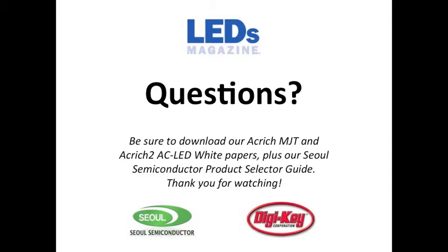So you talked about the flat top and the dome LEDs, and mostly I think you talked more about optical, and I might have a question there, but this person wants to know, is there an efficacy trade-off between the flat and dome type? That's a good question. Typically with a dome type, you're going to extract the light a little bit better. In flat type, I think I'm seeing 145 lumens per watt. In some of the dome types, I'm getting up to about 160. So it seems right now the dome packages have a little bit better efficacy, and it does extract the light a little bit better.